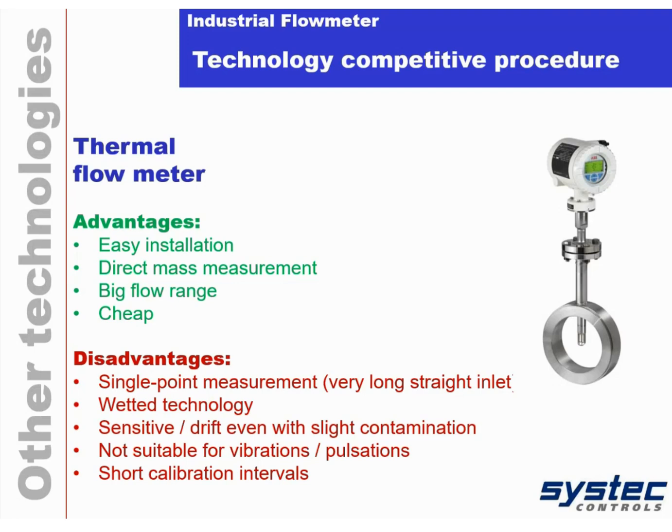Thermal flow meters, from my point of view, for process industries, be careful. If you are, for example, in medicine, and if you have bottled gases or something like that, thermal mass flow meters are good technology to use. But if you're measuring pressurized gas, if you want to measure combustion air and it's not filtered air and you have a rest of oil or soil or something like that, don't go for thermal mass flow meters.